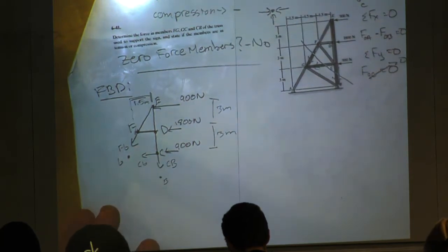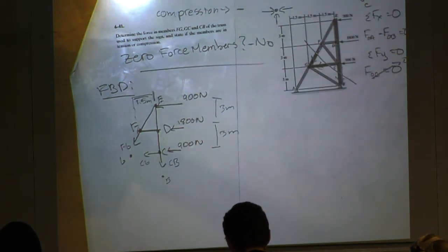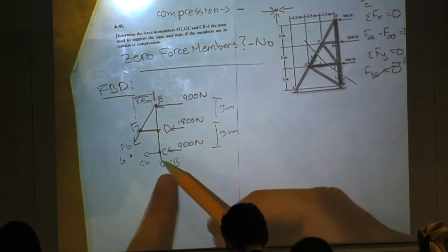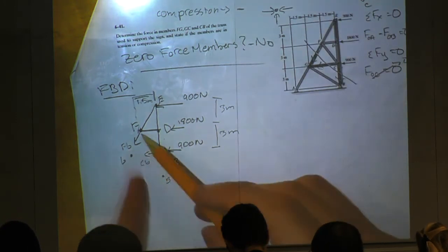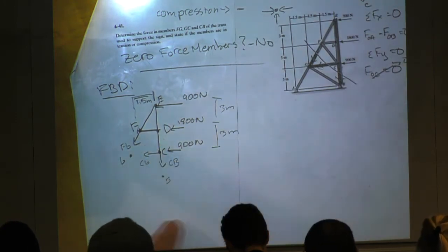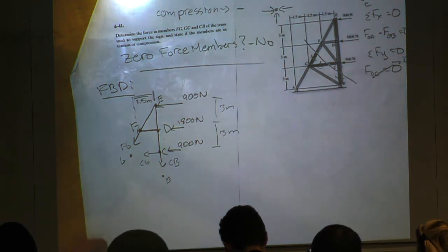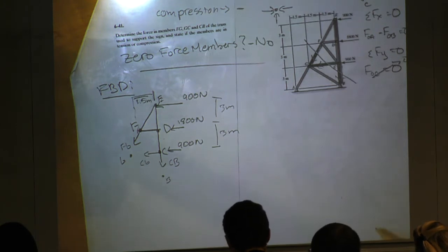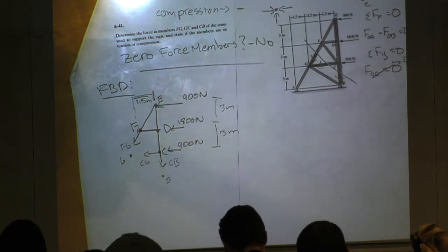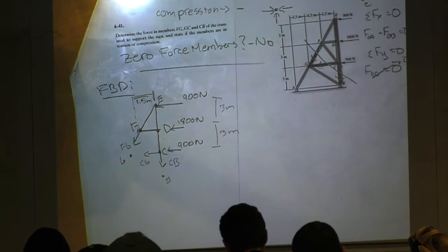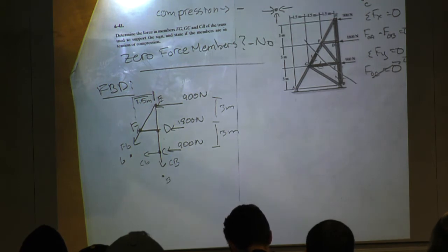Cool. So, all right, what about some force in the y? Again, we run into the same problem. I have a force here in the y, and this has also a component in the y. So that will give me 2 unknowns. And they won't be the same 2 as the other, so I'll have to have another equation. And what's my last equation? My moment equation. So I want to find a point by which I can take a moment. The cool thing about this problem is everything here can be solved using a moment about a point that is either on or off of the truss.